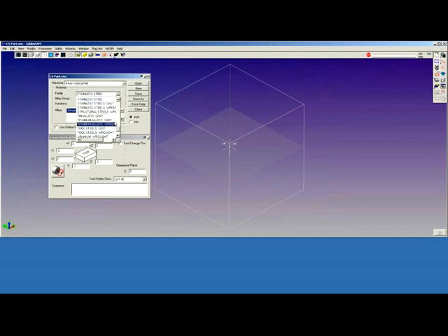I'm going to go with aluminum alloys in the wrought condition and bump the hardness up to 75 to 150 on the H scale, and I'm looking for 6061. It appears there in my selection set. So all the feeds and speeds generated by the system will be consistent with my material selection and my tool material. My input method will be inch, and my stock is defined as 2 inches in each direction, leaving the default coordinate system in the center.